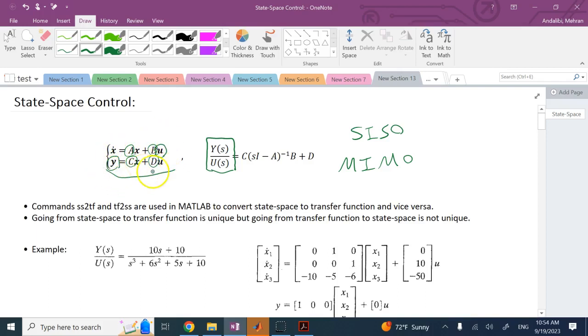So this is in general more compact. It allows much easier control, as we'll see in the next lecture, called pole placement or pole assignment for MIMO systems, and it shows many other advantages and many other analyses. It makes it a lot easier, like controllability, observability, observers, and a lot more. So in general, in systems with multiple inputs, multiple outputs, this state space is much more preferred compared to the Laplace. These differential equations are mostly first order, and they're easier to solve and also easier to simulate.